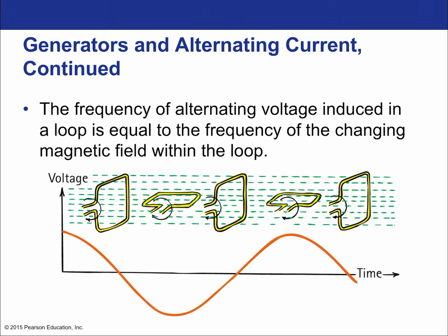All right, this is getting more into the idea, and we can see that if we look at the voltage, we can see these parts where it zeroes out. And it zeroes out every time the coil is in this orientation, because in this orientation, check out the velocities. The velocities of the free electrons are parallel to the green dotted line, which is the magnetic field. And whenever they're parallel, there is no force, thus no voltage. See, parallel again right here, parallel right here. Maximum voltage when the velocity is perpendicular. See, these are velocity vectors. And so that occurs with the maximum voltage, at least maximum in magnitude, even if it's negative. It's the magnitude that we care about, the distance from zero. A zero voltage means no current.